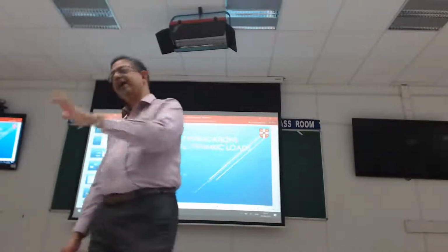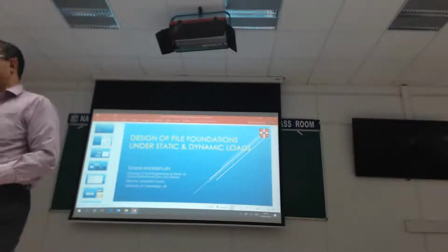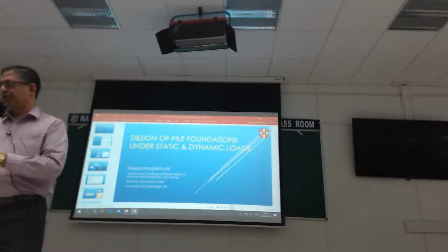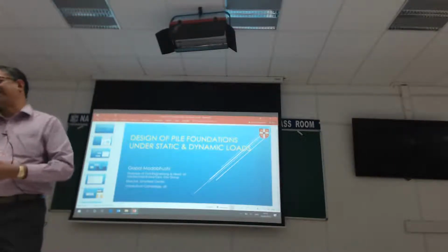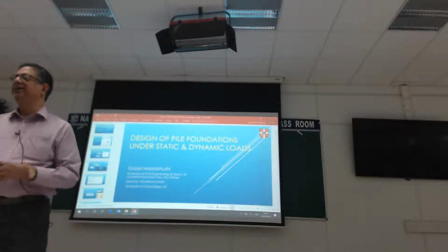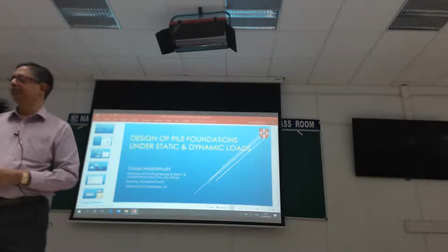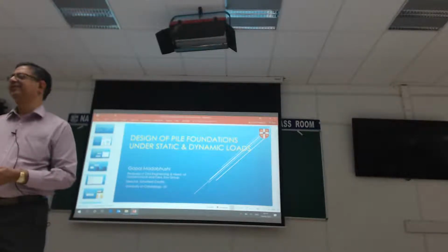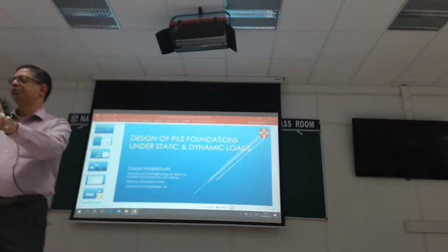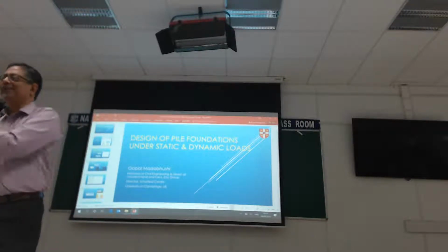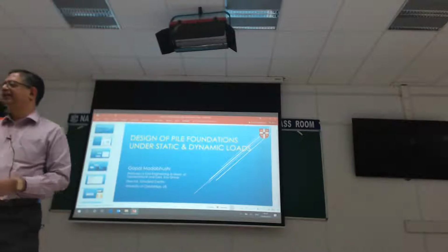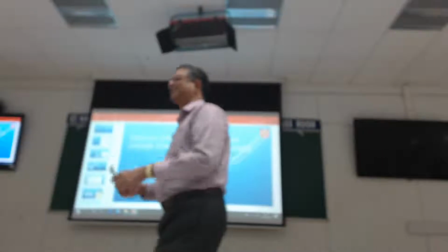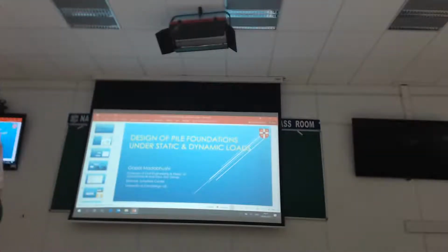But when you try to model the damping in the structure, you need to be careful that the model structures you're building not only have their eigenfrequencies 10 times bigger, but the damping also needs to be proportionally modeled. Typically we use Rayleigh-type damping, so there's an alpha M plus beta K. You choose your alphas and betas until you get the right response in the right frequency range. I had to learn quite a lot of structural dynamics, obviously, to do this properly.